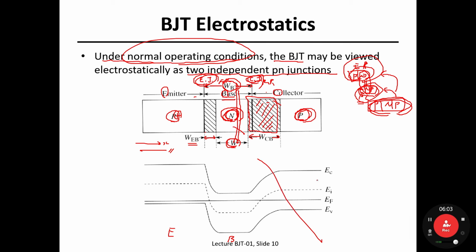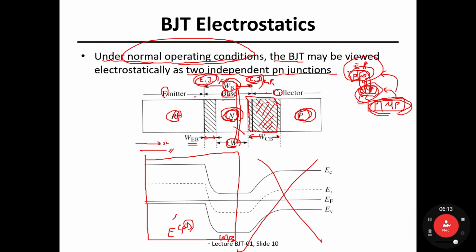Here, emitter side and base side. Just forget this part. Take a look at this part only. This is P plus, the base is N and is heavily doped. For the conventional PN junction diode, if I draw the energy band diagram along the x direction, this is the P side, this is the N side, and the Fermi energy level, the band diagram at thermal equilibrium.